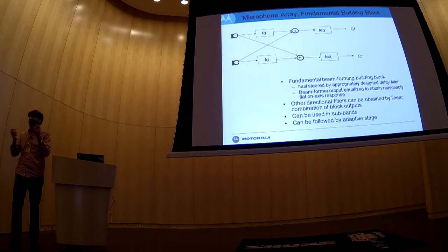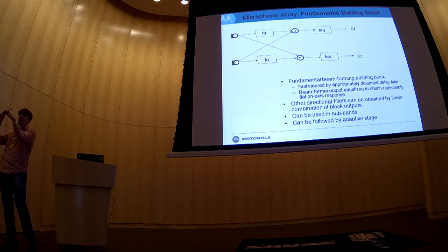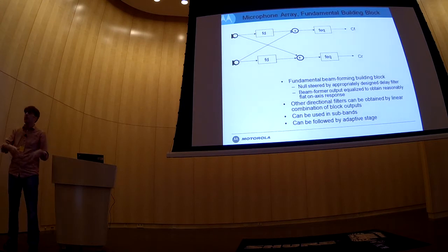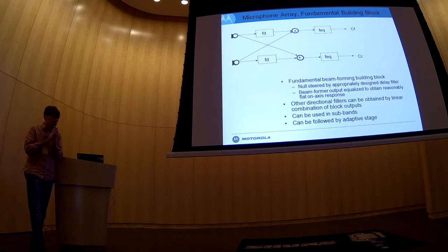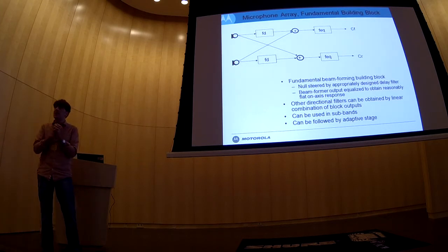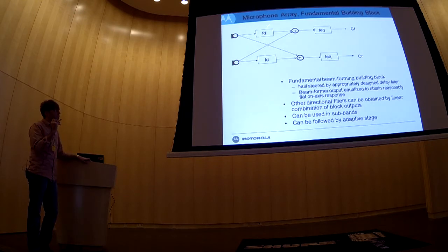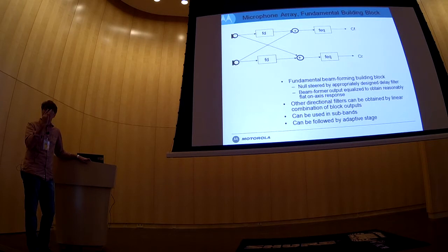So what happens is you have two or multiple microphones, and there's a fairly large structure in between. And what that structure does, and the porting of the microphone and all of that goes in there, results in complicating the life of the system designer. Because what it does, it creates the necessity of designing a proper delay filter that delays every frequency just right prior to the summation junction where the differential occurs.